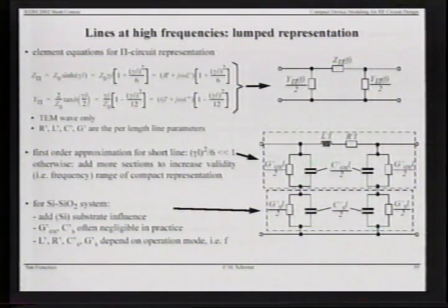There is a lumped, closed-form solution, basically, and terminating that after the first frequency term gives us a representation which we can put into a compact model that is shown here, and that represents the TM case, where we have frequency-independent elements, an inductor and a resistor in series, and then we have a parallel network. This is again the pi equivalent circuit for a short line.